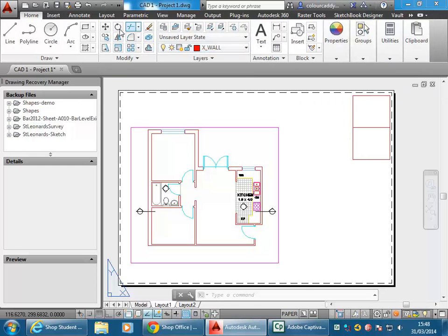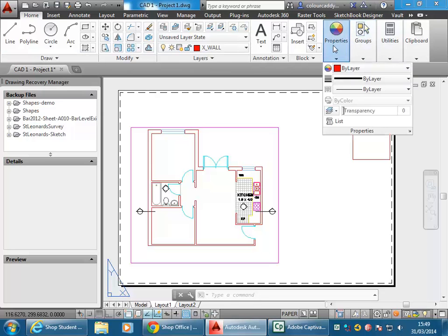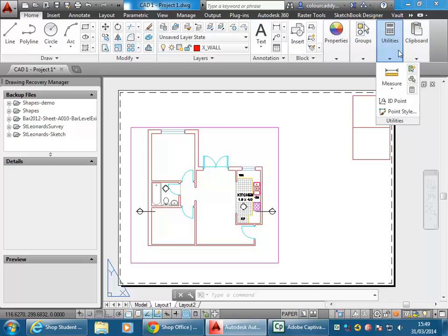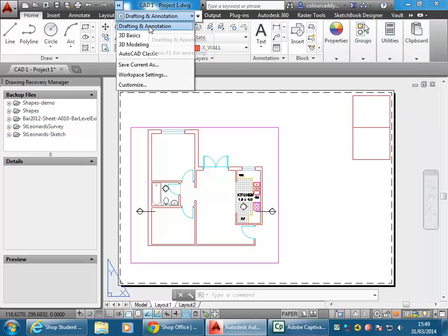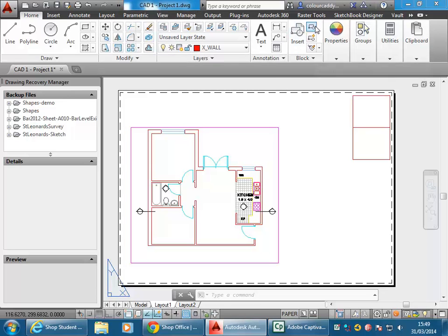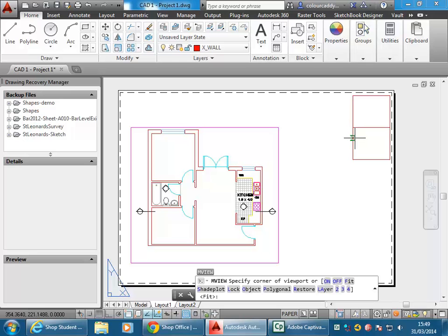I might just show you the shortcut. Yeah, no, so you'll find that a little bit with AutoCAD. Unfortunately, with these different workspaces, some of the basic workspaces don't have all the tools you need as buttons up here. And so I don't want to get you digging too much. I'm just going to tell you the shortcut, which is MV. So MV is the shortcut for Make View.